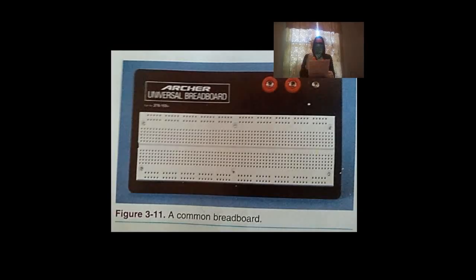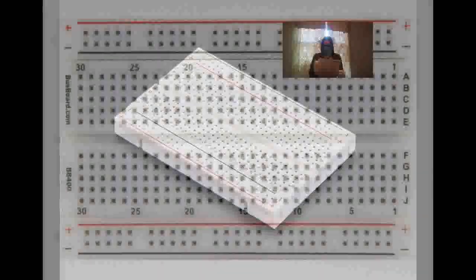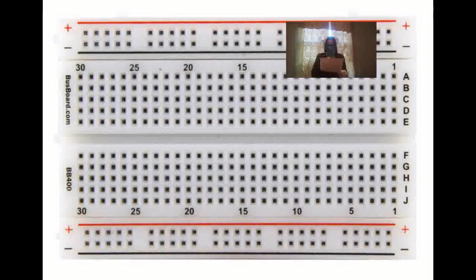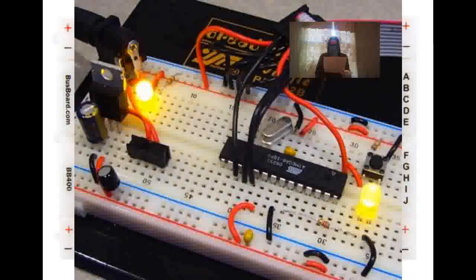Breadboards. A breadboard is a useful device for learning about circuits. A breadboard consists of a series of holes aligned in rows across the entire surface of an insulation material, such as plastic. Copper strips are run in parallel under the rows of holes and are used as conductor pathways. Electronic devices such as resistors and transistors are inserted into the holes. Jumper wires are then used to make additional connections between the devices. The breadboard provides an easy system for constructing circuits quickly.